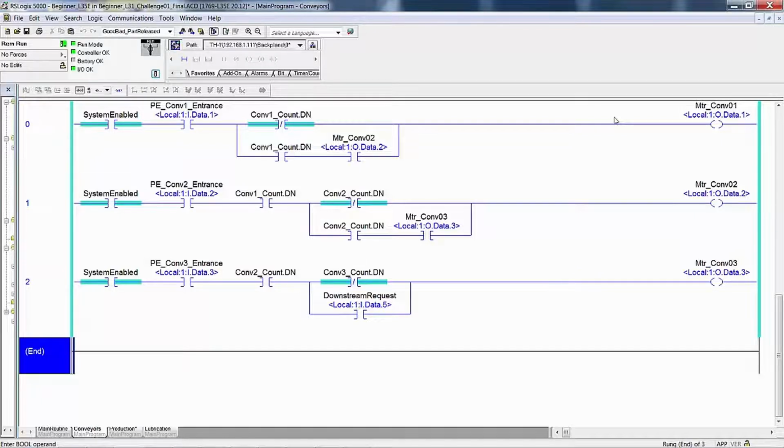Okay, we were on page 253, 254. We switched PE1 off and we left it off. Did conveyor 1 counter increment to 1 when PE went to the off state? Yes, it did. Select the conveyor logic. Are any conveyors running? No. While observing both the production and conveyor routines at appropriate moments, switching back and forth, switch PE on. Check conveyors running and then switch PE1 off and check the count increment.